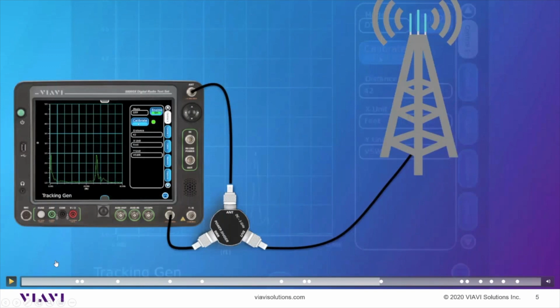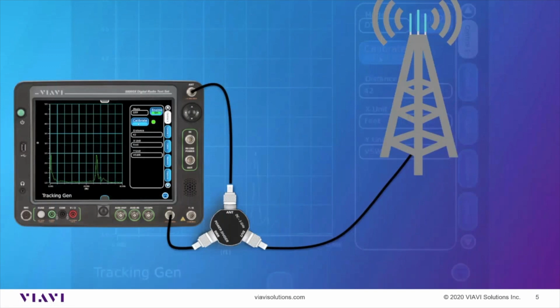If in a troubleshooting mode, what you could do is run the VSWR, and if your VSWR is really high, you don't want to just run out there and call the climbers and have them go up and change the antenna. You want to make sure what is causing the problem. So if you run your VSWR sweep and you're getting a really high VSWR, 4 or 5, or maybe even 3, which is too much, then you can use this distance to fault, and it'll tell you where the fault is.